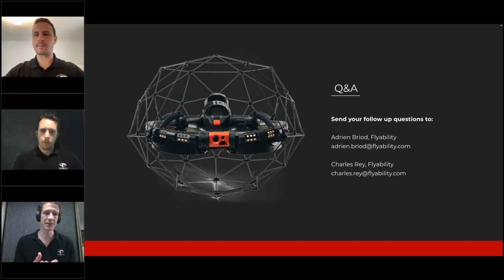Now, if the question is about close-up visual inspection, where you would like to cover the tank systematically at a certain resolution, maybe say 1 millimeter per pixel, and you would want to remain 50 centimeters, for example, from any surface, that could definitely take tens of batteries. That's a use case that several of our customers do, and that's where the coverage check that Zach mentioned is very useful, since it can take lots and lots of batteries to do such a visual coverage.